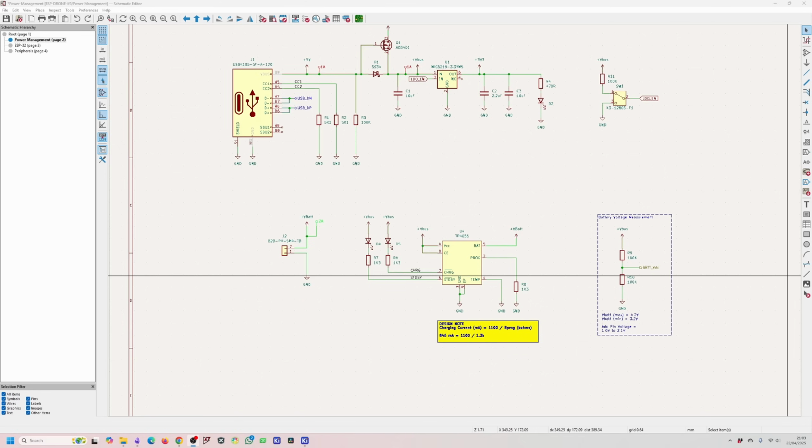We want to double check all the connections that we've made in the schematic. Now this might seem repetitive, but it's so important it deserves its own section. Double check all your connections. Even a single incorrect connection in your schematic can lead to a non-functional PCB obviously. So it's much easier to fix these errors now in the schematic stage than later when you have a physical board in front of you, or when you're halfway through your PCB design, realizing you've missed a connection and then having to redo a lot of the PCB design just to correct it afterwards.